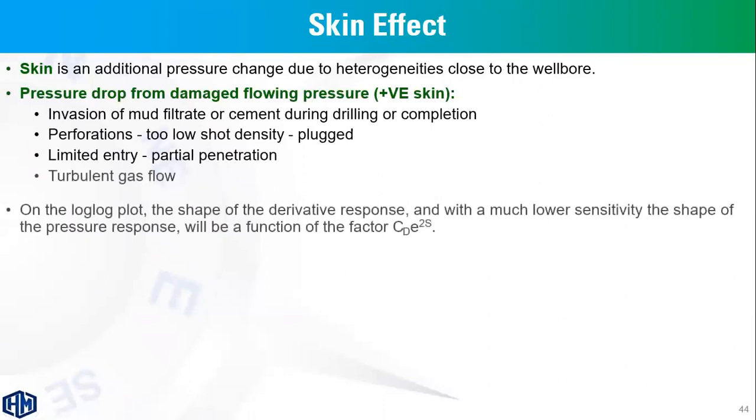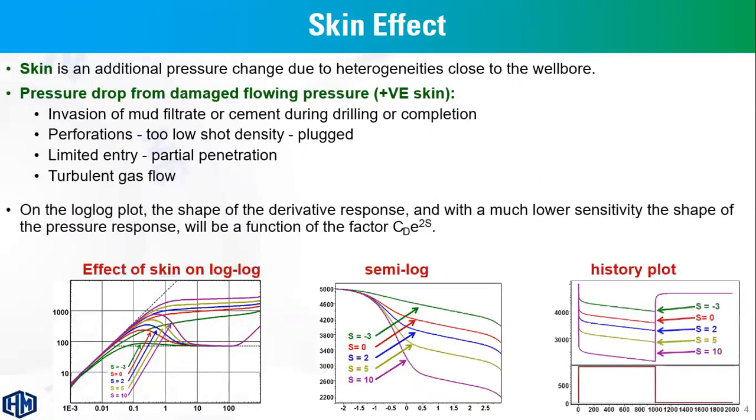A skin effect, as mentioned, is an additional pressure drop due to alteration in the region around the wellbore. In case we have damage, we will have positive skin, typically due to invasion of drilling fluids and completion fluids, or maybe the efficiency of the completion itself.